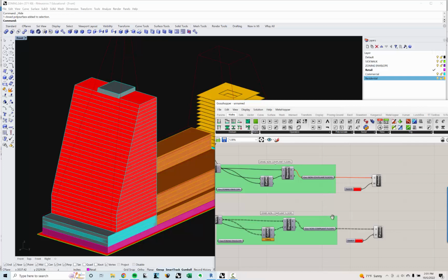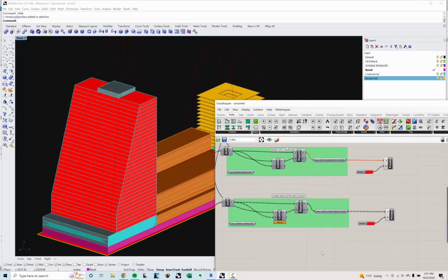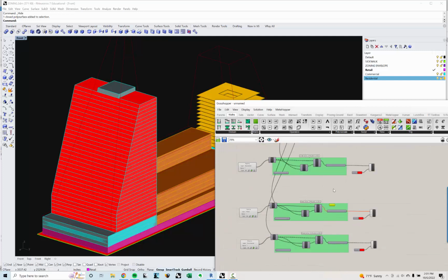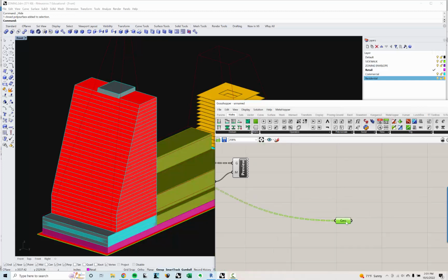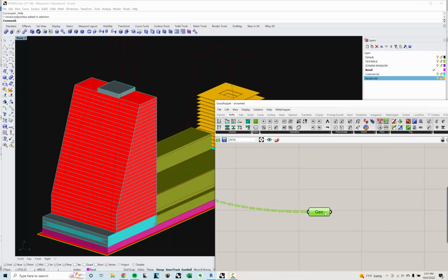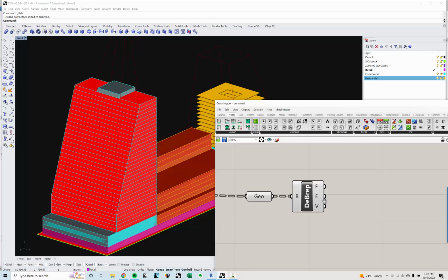So what I'm going to do is, using this same dispatch component, I only want to grab the floors that are compliant. So I will start up here with my residential. So I'm going to grab these, and I have those. What I want to do is get the bottom floor plate and get the area of that. So I'm going to do a deconstruct brep. Okay. So now I have all the different faces of each one of these volumes, and if they're rectangles, I should have 6. If they become different shapes, I'll have more or less.